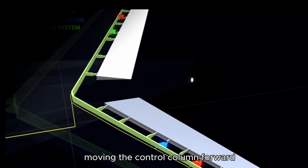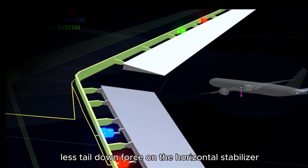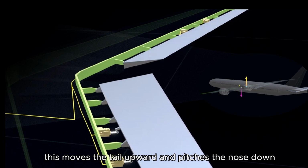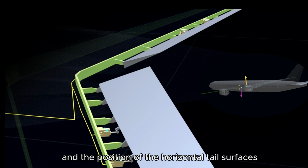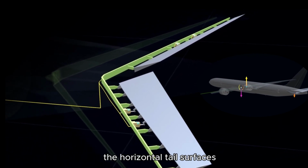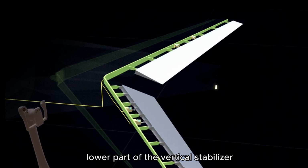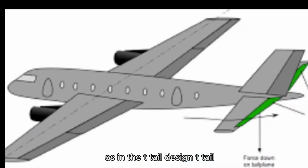Moving the control column forward has the opposite effect. In this case, elevator camber increases, creating more lift, less tail-down force, on the horizontal stabilizer. This moves the tail upward and pitches the nose down. Stability, power, thrust line, and the position of the horizontal tail surfaces on the empennage are factors in elevator effectiveness controlling pitch. The horizontal tail surfaces may be attached near to one of the following: lower part of the vertical stabilizer, at the midpoint, or at the high point, as in the T-tail design.